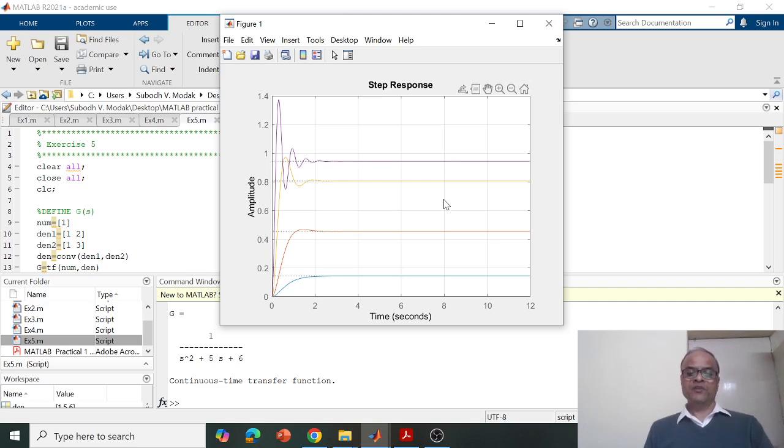So this particular exercise has helped us to understand how the gain of the proportional controller affects its performance, correct? Also, one drawback of increasing the gain is that with lower gain the system didn't have overshoot. You can see for gain k equal to 1, there was no overshoot. But with gain k equal to 100, the system is overshooting the desired reference value, and it is oscillating about the final steady state value. So this is the drawback of increasing the proportional gain k.